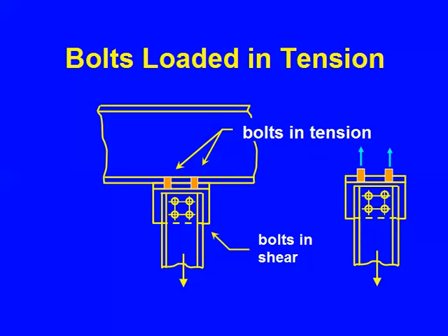Put on the known forces, put on the unknown forces as unknowns. Write the equations of equilibrium. Sum of forces in the vertical direction, of course, will give me the force in the orangey bolts, which are the bolts that are acting in tension. The presumption at this point is that the total load is divided by 4 in tension. It's a little more complicated than that, so we haven't quite finished with this.